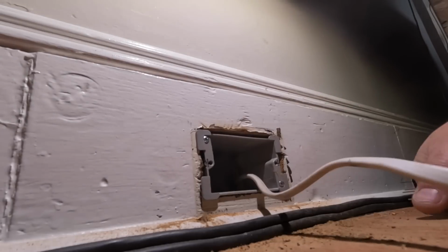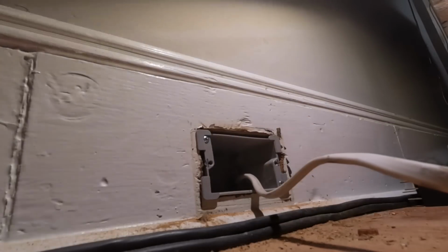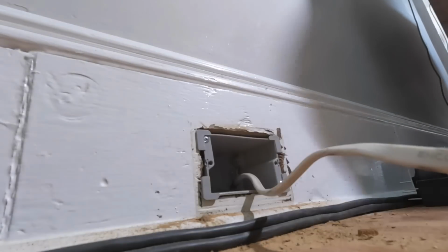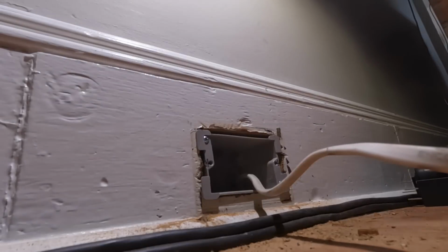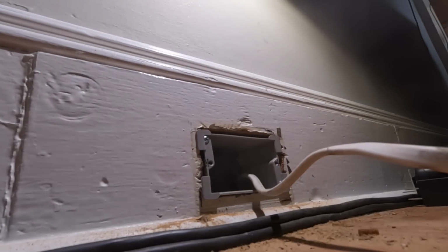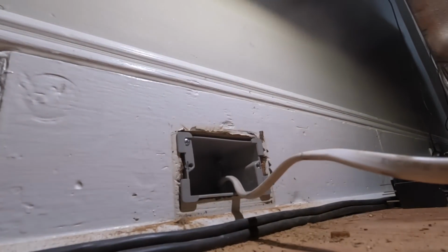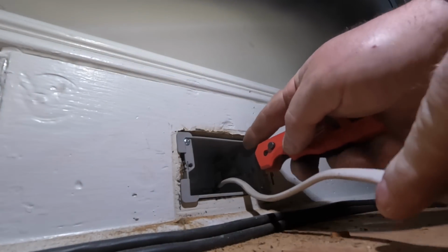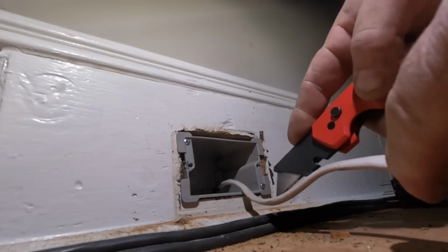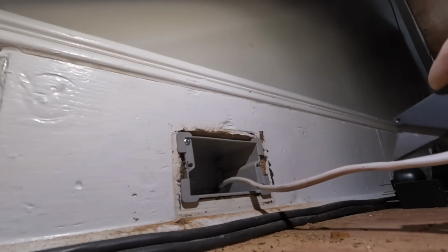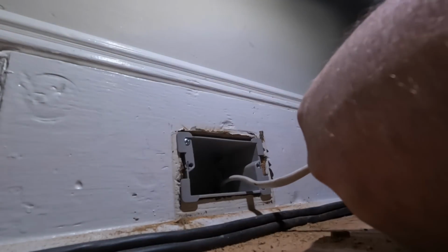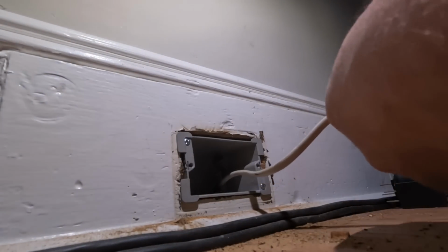You just want that box to fit in there, and then of course the cover plate's going to cover up any discrepancies on the outside of the box. But generally the code says no more than 1/8 of an inch larger than that box. Otherwise you have to repair it. And so that's what we're working with here. And this is a good installation. Now I'm just going to use my utility knife to cut back down the middle of the non-metallic sheath cable to break apart the sheathing, and then I'll come back in and try to cut it.